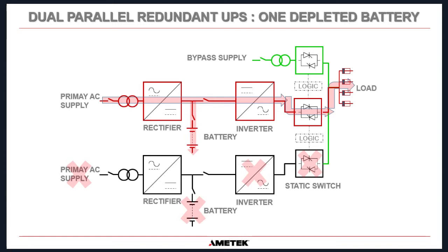Okay, connecting a bypass supply in parallel with an inverter supply is a very bad thing. So what happens is when this inverter on the bottom UPS switches off, we actually turn off the bottom static switch here. It goes open, and we just allow the healthy UPS to supply the load circuits at this point here. Okay.